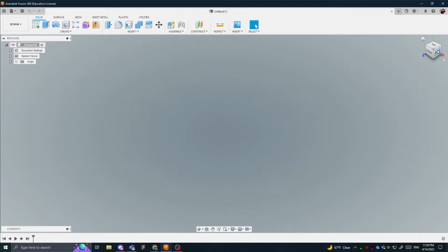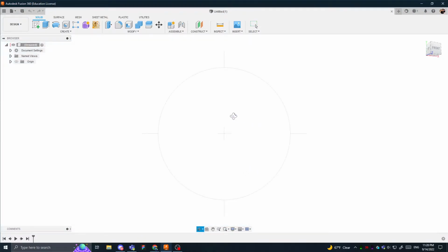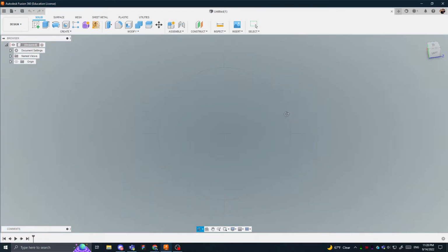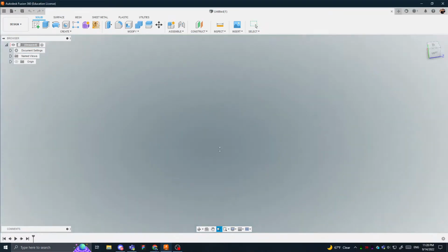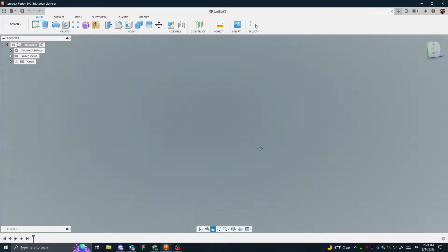So this is our workspace. This is where we manipulate our 3D view. You can click and drag in the view cube on the top right to orient yourself. The pivot point is showcased in the middle. If you middle mouse and shift together, you get the orbit, and you can see the orbit location is the green dot here. You can also orbit with the tools down here, so you can orbit like so, or you can grab this ring here and rotate like so. You can push look at. This is useful when we actually have something to click on to look at. Pan is this hand tool. Zoom is to zoom in and out, which is also your scroll wheel. Pan is also middle mouse drag.